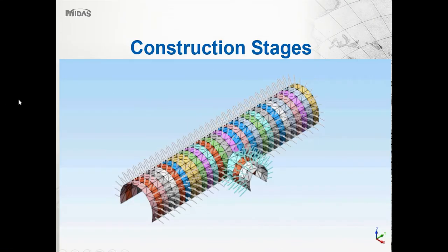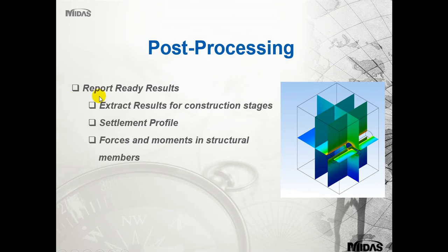post-processing. So in the post-processing, we'll look at some of the report-ready results. We'll look at extracting the results from the construction stages. We'll look at the settlement profiles, the deformations and displacements. We'll also look at the forces and moments in the structural members in the form of the rock bolts and the shotcrete. And we'll also look at the cutting planes. So going back to the model,